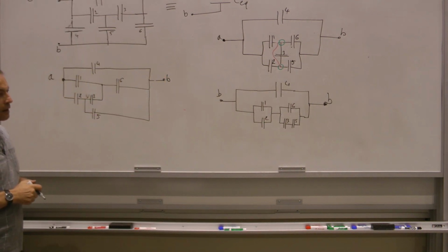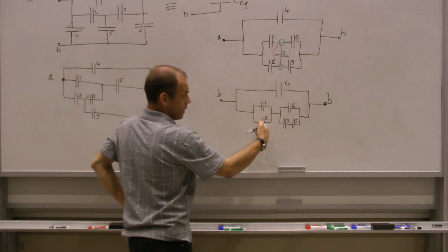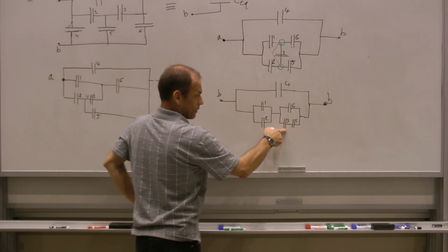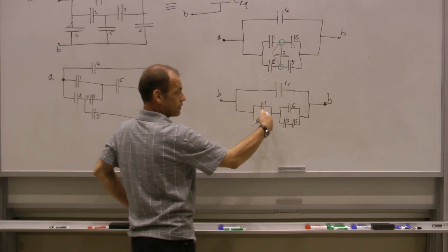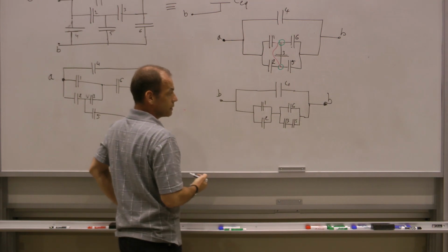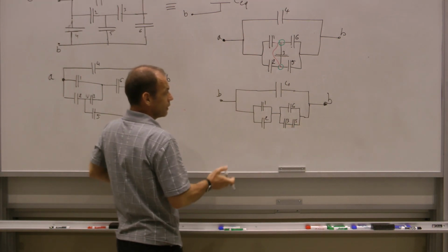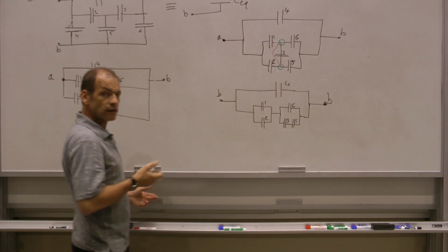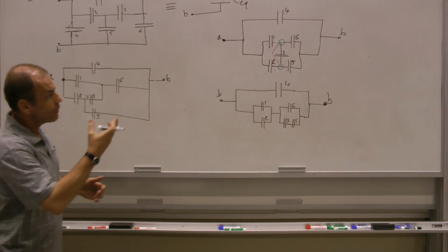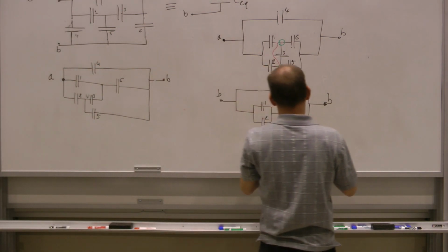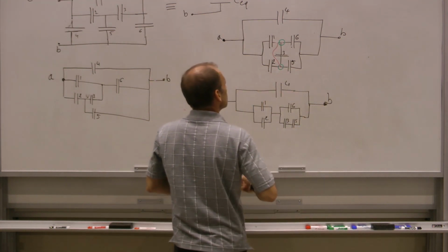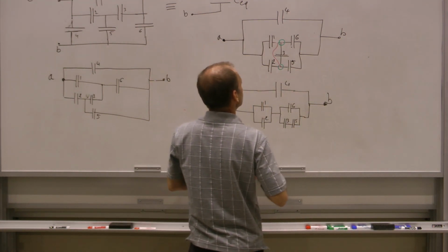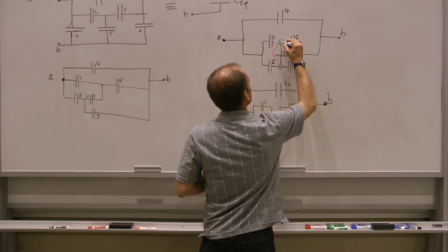Voilà. So now we have a set of 2 capacitors in series, in parallel with capacitor 6, and then we have another set in parallel. The whole thing is in series, and then another set in parallel. So now this is totally manageable. Another way to draw it would be to say that I could draw the lead to do this business.